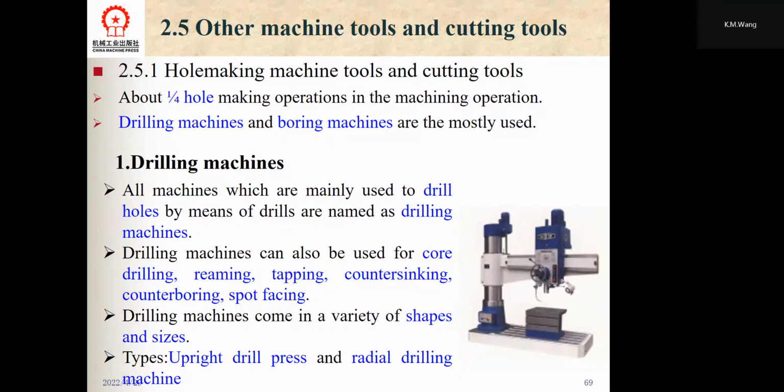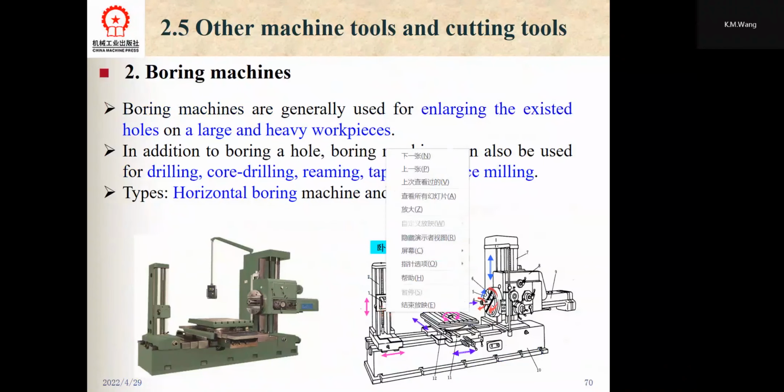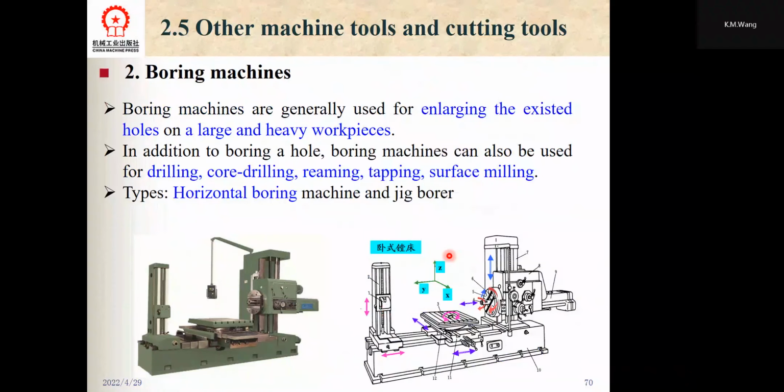And then we will introduce the boring machine. The boring machines are usually used for enlarging the existing holes on a large and heavy workpiece. In addition to boring a hole, boring machines can also be used for drilling, core drilling, reaming, tapping, surface milling,